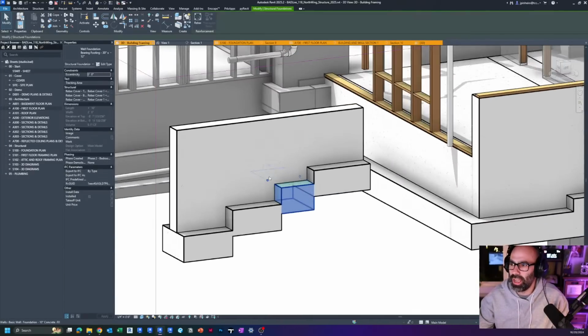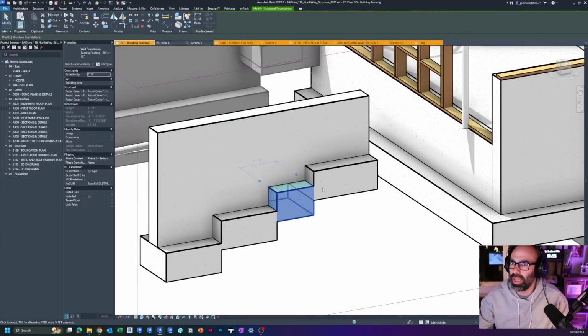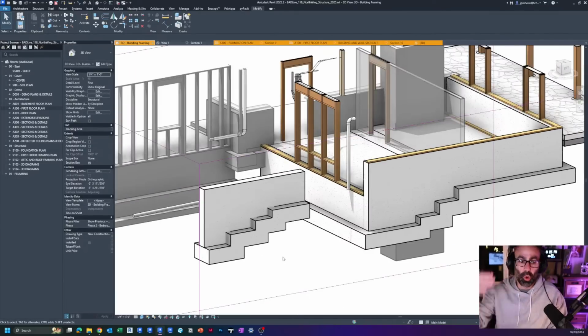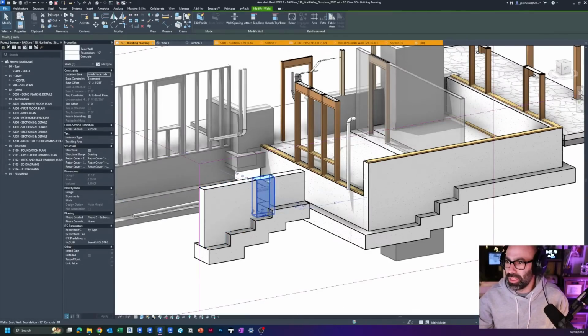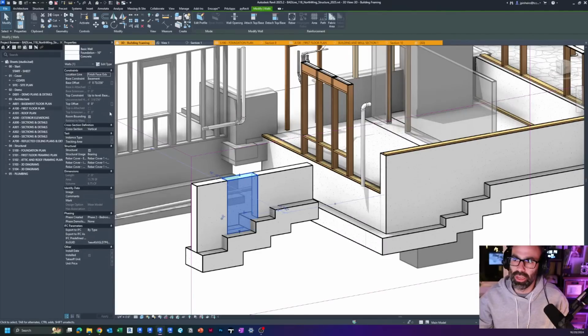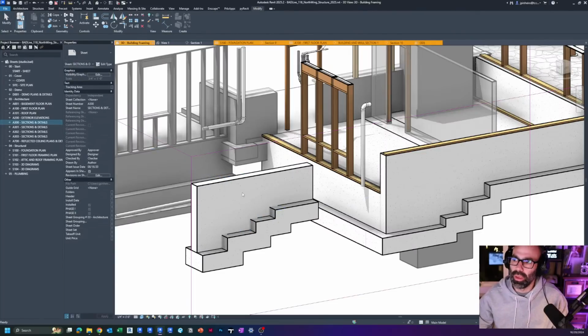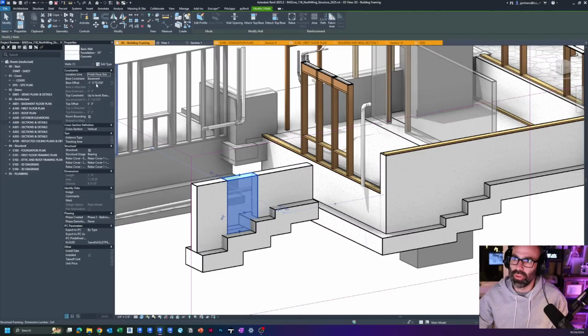And then I'm offsetting this footing by 1 foot, 1 to 2, whatever that ratio is. And you can see they clean up pretty nicely, right? So I'm just going to pull it. I'm being loose right now, but you get the idea. Okay. And so that's one way to quickly create a step footing, right? That's just kind of the way I like having these 3 different walls, because then each wall segment can also generate the information as far as on the left-hand side for the properties of base, offset. There are different properties within it.